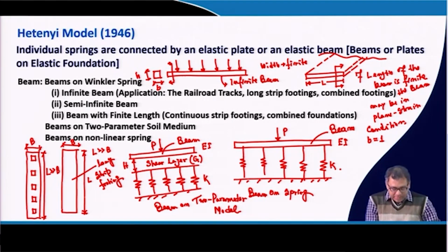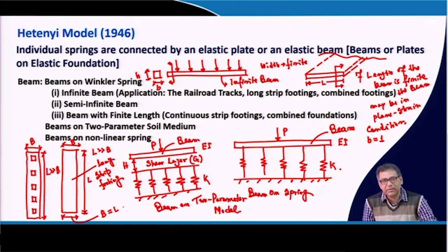Another way is that the width of the foundation is taken as the length of the beam, and in such case the beam will be under plane strain condition, and you have to consider a unit width equal to 1. So, this type of situation I can model in two ways. One is an infinite beam with finite width, another is a beam under plane strain condition.